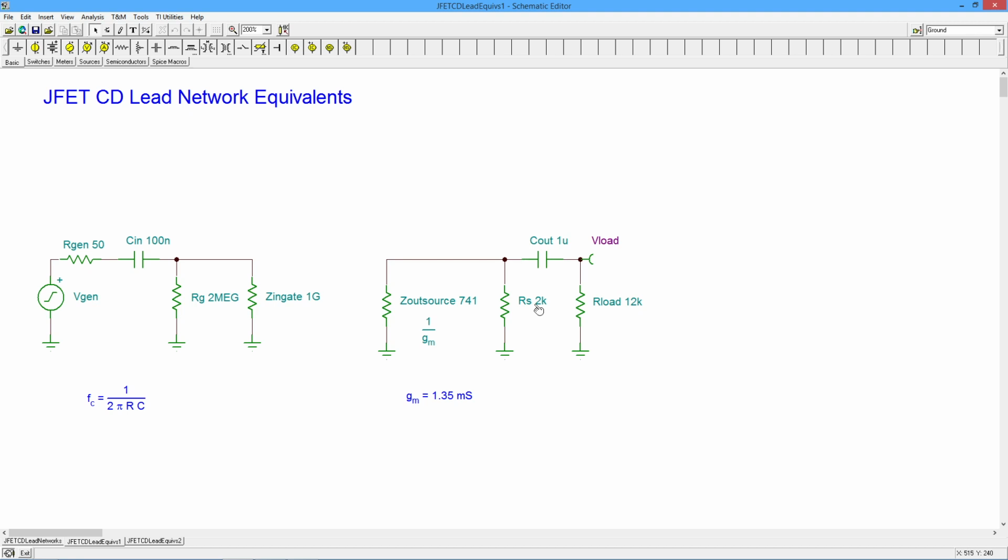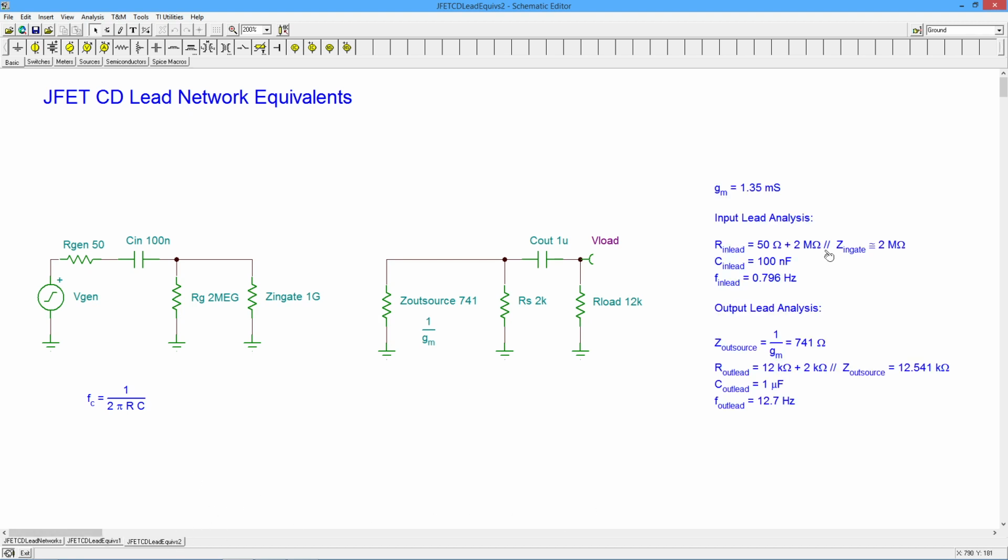Think of a simple DC circuit, and let's say you've got a cap charged up and you're going to discharge it. What does it discharge through? So these are in series. I've got 12K in series with this parallel combo. Once I get that R and C, I plug it in the formula. What do those numbers work out to? Bingo! It's all done over here.